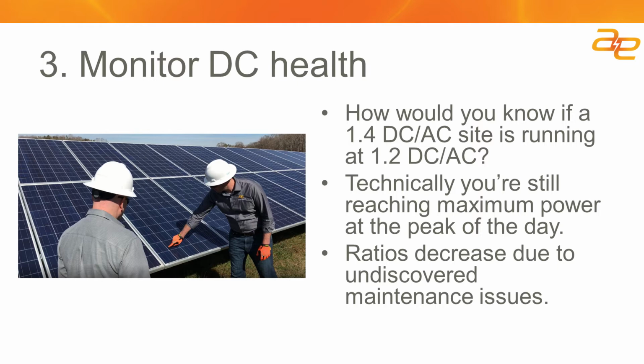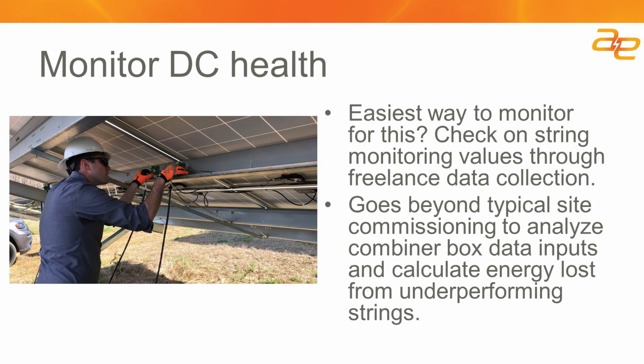And then finding the individual problems on DC health is maybe one of the most challenging O&M tasks for a solar site. So there's been a lot of reporting recently with the really cool technology, putting an infrared camera on a drone, flying it over a site, and finding all of the module hotspots to help you go out and diagnose some DC health issues. I think it's interesting and indicative technology that'll give you some focus on where to look at a site.